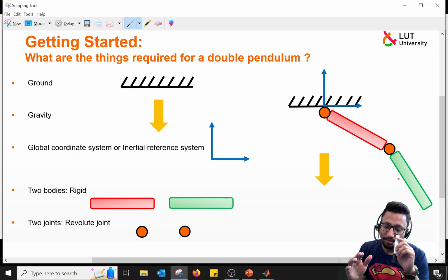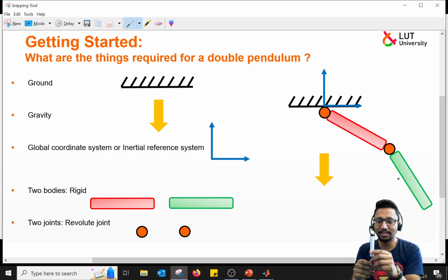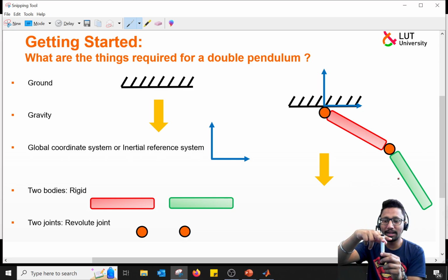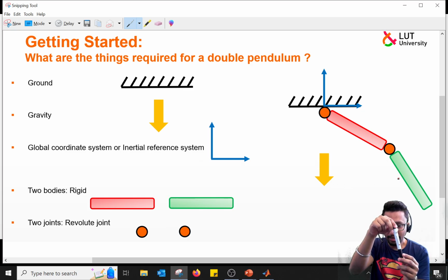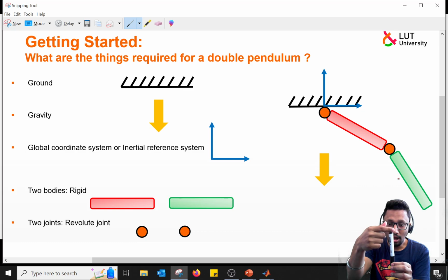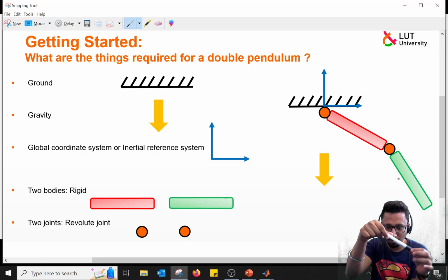Now, the moment I say let's constrain this system over here so that it acts like a simple pendulum, I'm constraining this point here, and this will execute an oscillation motion, correct? This will have a motion like this in space in 3D. Now, if we put a revolute joint here, we know that the revolute joint helps this particular body execute motion only in this format, right?